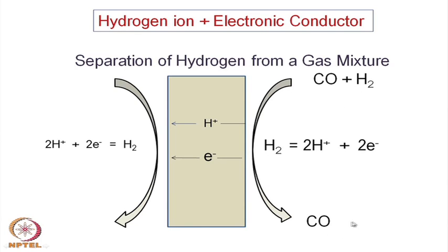So, carbon dioxide will come here and hydrogen will go on the other side. So, you can get hydrogen on the other side after the reforming reaction of the hydrocarbon. So, by the process of two things, this can be done in the same chamber also, and if you have a reformed gas, you can separate it from this using a MIEC membrane, the so called dense membrane.